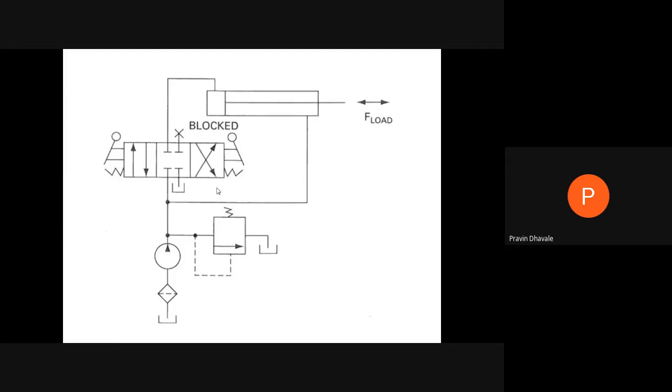That will help to increase the extension speed of the piston in case of a regenerative circuit. Are you understood? Yes, sir.